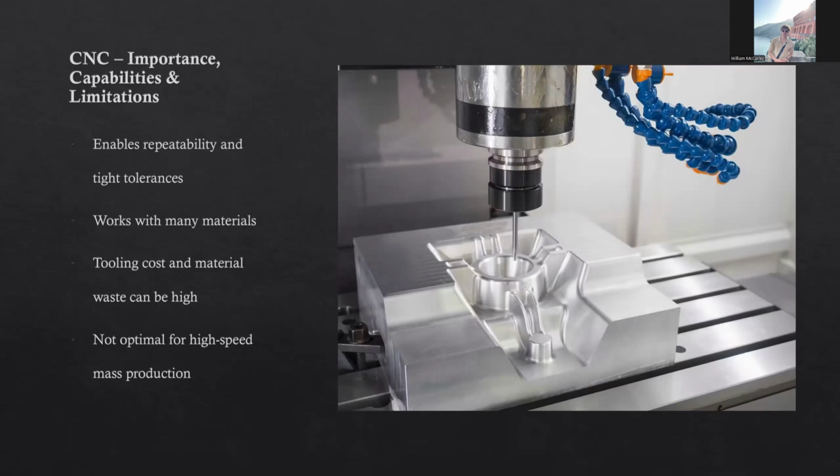But not everything with CNCs is perfect. The setup and tooling can be very expensive, some of them running up to $300 an hour if you want to externally rent a CNC machine. And it's not great for mass production. It does one at a time most of the time, unless you get a more expensive machine.